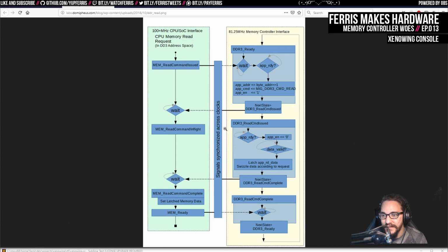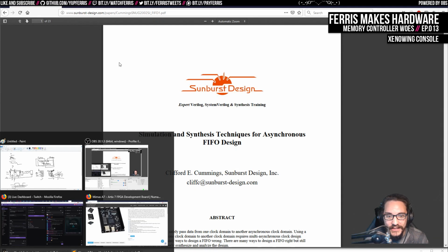So the general consensus is be very careful if you're crossing clock domains, and that includes pulling inputs to your chip. Now, sending outputs, don't worry about it, right? Because that's the other side's problem. And there you might have to specify constraints on your output pins to say, well, we need this kind of timing relative to our clock such that you don't have a lot of skew between the different signals. So you need to specify that as part of your design constraints, which again, if I pull up this constraints file,